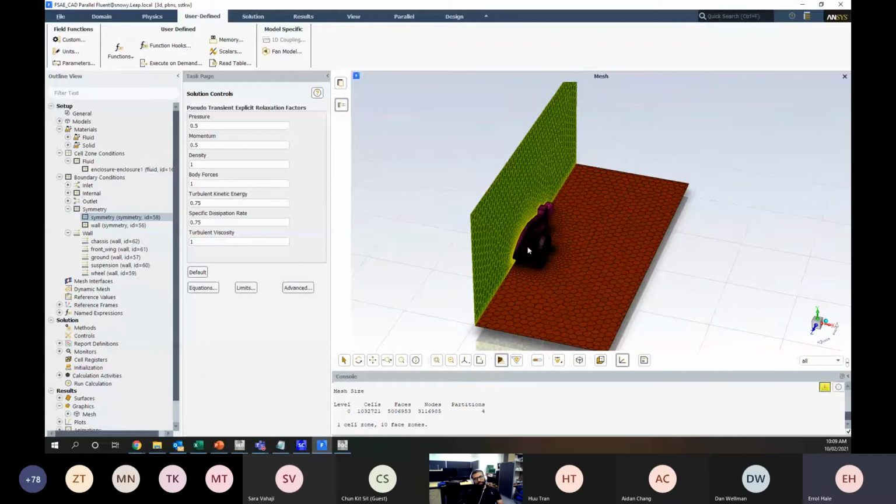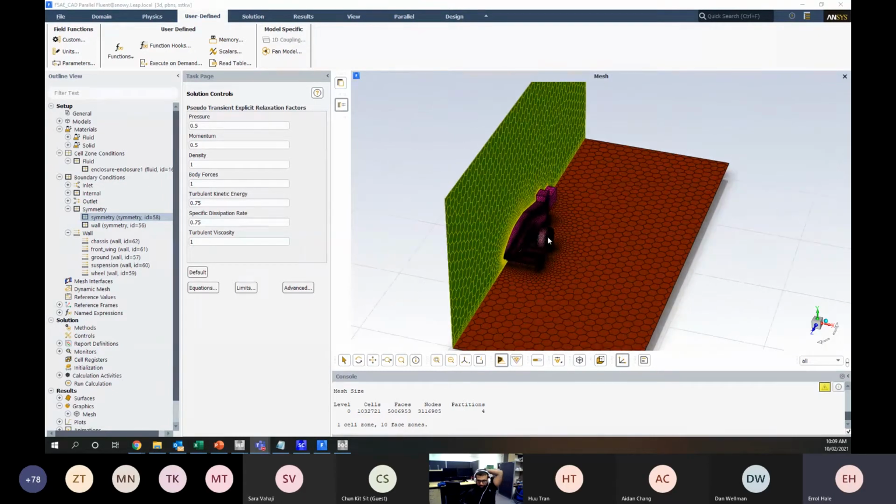Another way you can do it is you can have a rotating domain. So you can have a kind of annular shaped domain, ring shaped. You wouldn't have the whole ring of it, but enough that the flow's coming in at a circular angle, if that makes sense. They're much more high fidelity. So when you're doing flow, any yaw angle on an aerodynamic on a vehicle is much bigger because you're doubling the amount of elements you're using.